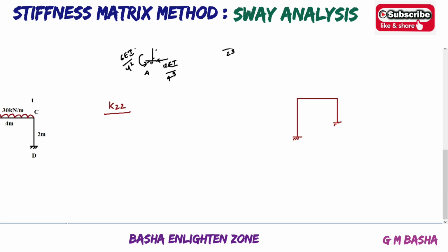So already we release the structure at B and apply unit rotation at B, that is K22. Okay, if you apply the moment, you will get sagging like this. Similarly, the same moment applied here, you will get sagging like this. Okay, if this will be K22, you will get next force will be K32 here, half of the moment distributed here, and again.